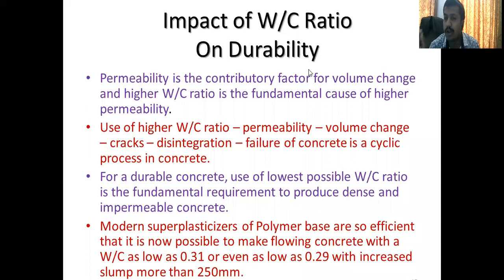And if there are voids, and you drop some water on that concrete structure, there is no single crack, I am telling you, but you haven't compacted the concrete. If you pour some quantity of water, you will see that some water is percolated through that structure.